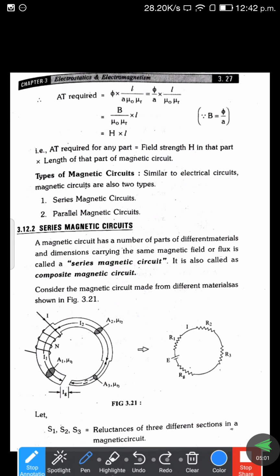So because of that reason it is a constant. Sometimes we are taking the constant, sometimes we are taking it as unity. Reluctance is not a problem for air, but the rest of the three things will be essential. Here we are taking three different metals or magnetic materials combined together, and the same flux is flowing through that. That is what we are taking as an assumption.